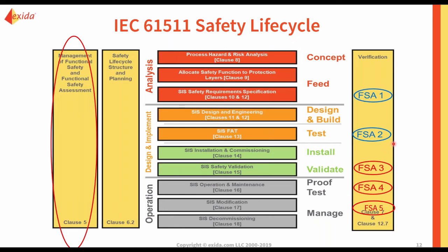So when you hit the push button to open it, it essentially was just staying closed. And so something that would have been easily identified had they done one of those earlier checks turned into a multi-million-dollar incident, and then they had to go through the whole thing, design another system, and bring that down to the bottom of the ocean. So that's where following through with the overall functional safety management and doing those functional safety assessments periodically can help to avoid bigger problems down the line.